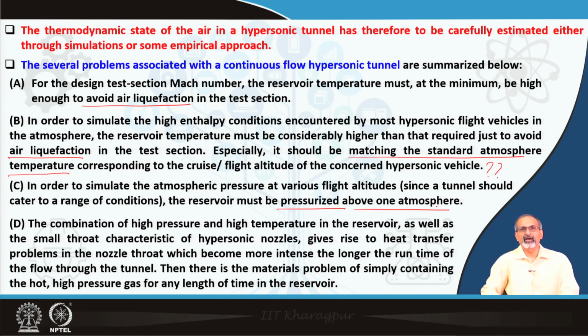The combination of high pressure and high temperature in the reservoir, as well as the small throat characteristic of hypersonic nozzles, gives rise to heat transfer problems in the nozzle throat, which becomes intense the longer the run time of the flow through the tunnel. This will aggravate the situation further. Then there is the materials problem of simply containing the hot high pressure gas for any length of time in the reservoir. So, there are multiple challenges to be faced.